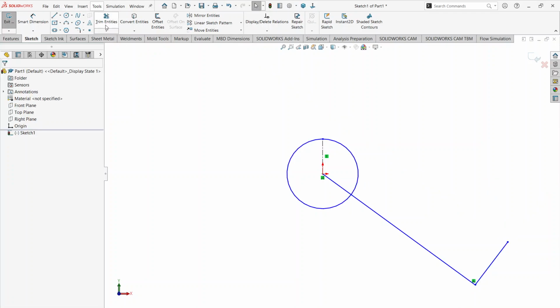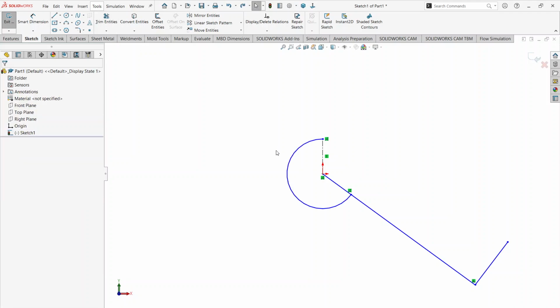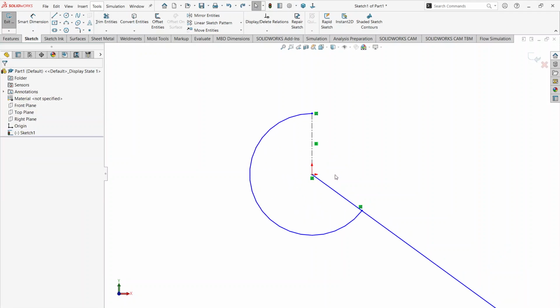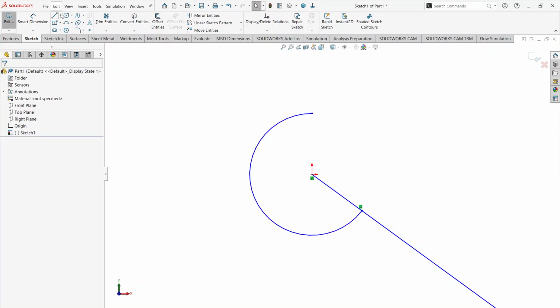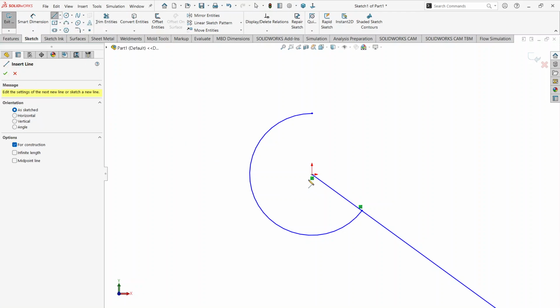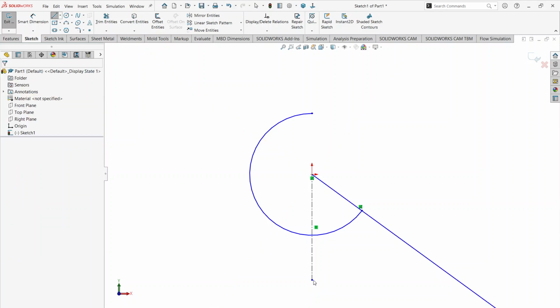So I know that I can trim my entities for the areas that I don't want, which would be here, here. Hold on. Maybe it is better that instead of creating a sketch here, create a vertical sketch. So it's gonna help me in the trimming.